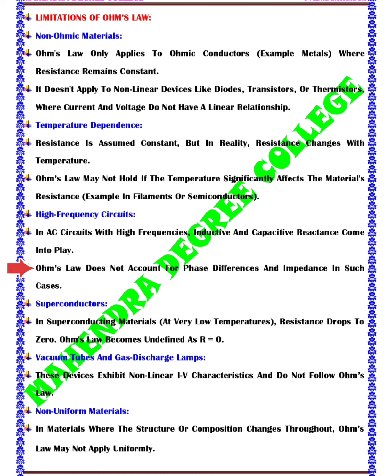Ohm's law does not account for phase differences and impedance in such cases. In simple terms, Ohm's law, which states V equals IR, voltage equals current times resistance, primarily applies to simple DC circuits with purely resistive elements. In AC circuits or circuits containing reactive elements like capacitors and inductors, where impedance and phase differences exist, Ohm's law needs modification or extension to account for these factors.